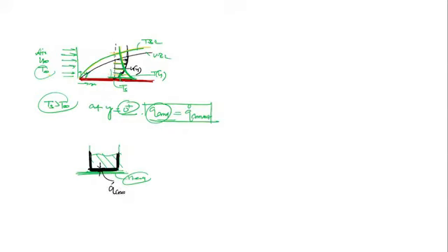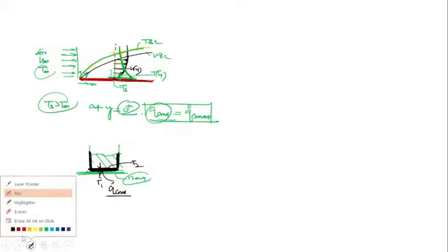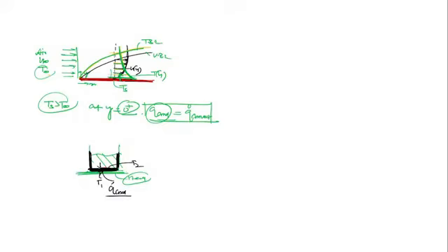Q conduction. This side is at temperature T1 and this side surface is at temperature T2. This temperature difference causes the temperature gradient, and that causes conduction in the solid. Now, when this is at temperature T2, the fluid adjacent to the surface is also at the same temperature. Any fluid layer on the surface is at the same temperature, but what about this layer of the fluid?